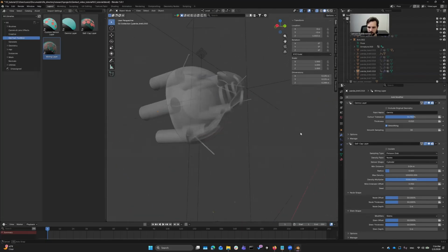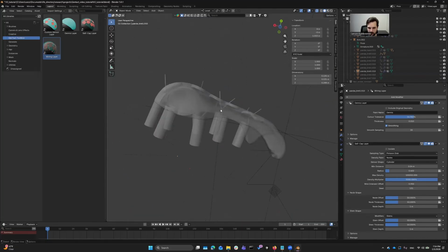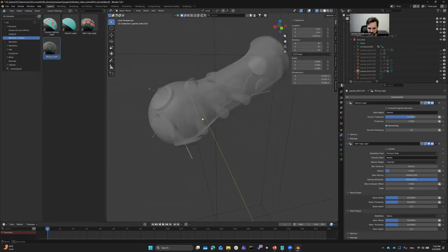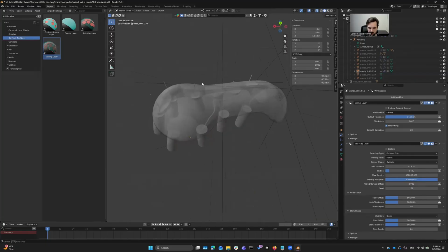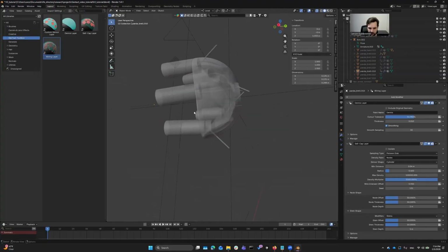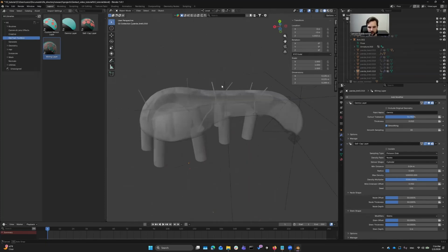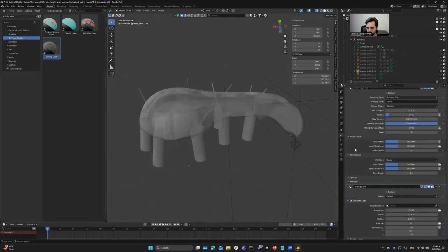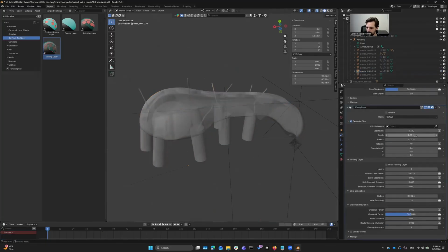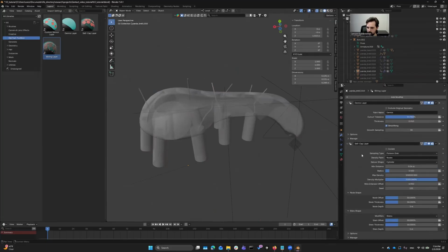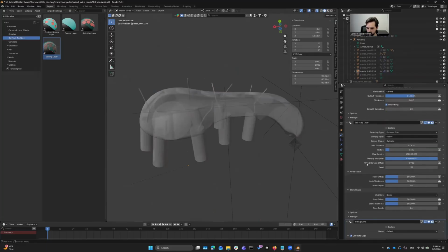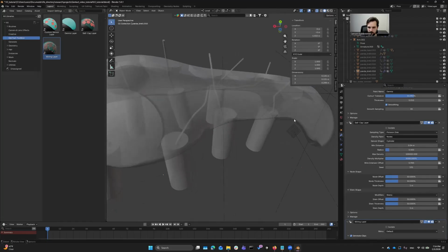It's a little goofy, but what you'll notice is that there are wires going towards the centers of these nodules. They're a little offset, but they're connected to these cylinders, which will be our clips sticking outside of the shell that will connect with an Arduino or a microcontroller. So let's clean this up a bit. Let's go down to our wiring layer. Actually, let's start with our self-cap layer, and we will lower this wire intersect offset. I'm just going to bring this down until it intersects with my sensor.